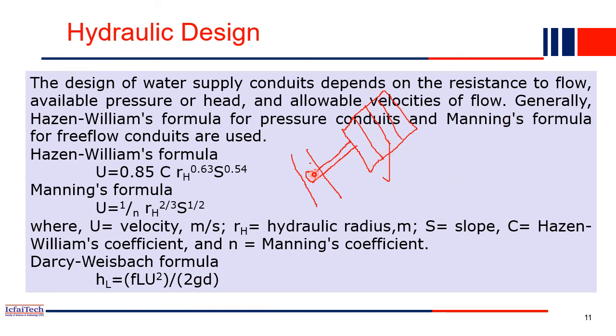So now based on that, basically we can design what will be the diameter of the pipe. So design means basically here we are finding out what is the diameter of the pipe, what is the grade of pump required for this treatment plant and all. Okay, so depending on how much requirement we have, we can design the diameter of the pipe. So for example, you have to distribute maybe every day 1,000 liter, or more than 1,000 liter, for example 10,000 liter you want to distribute the water in a small village. 10,000 liter, they're very small.